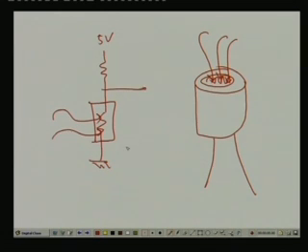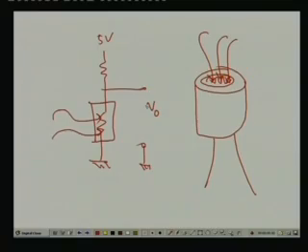And this voltage, obviously what will happen if the light falls, you will find that this voltage will change, right. So, if I measure, because this resistance will change, so this voltage VO across this will also change. So, this VO can be utilized for making so many sensors or switches also, right. I can use this photoresistor as a switch also, clear, because this voltage will change as the light falls on this.